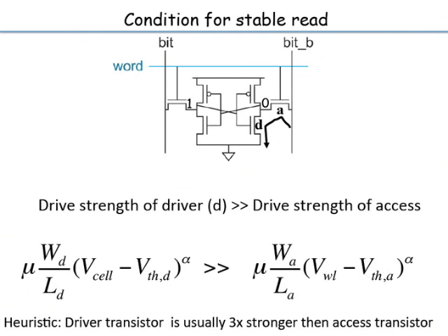So there are multi-sided constraints to the design of the SRAM cell. Everything is kind of coupled together. So you have to look at all these factors and design the SRAM cell. So typically SRAM cells are designed by specialists in these foundries. They will sit and design these SRAM cells, and very rarely do people design their own cells. You just take those cells and use them, because those cells designed by the foundry have gone through all these considerations and then they come up with the design and the layout.